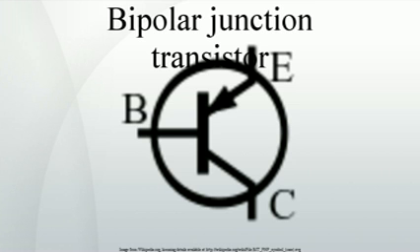Gummel-Poon charge control model. The Gummel-Poon model is a detailed charge-controlled model of BJT dynamics, which has been adopted and elaborated by others to explain transistor dynamics in greater detail than the terminal-based models typically do. This model also includes the dependence of transistor beta values upon the direct current levels in the transistor, which are assumed current-independent in the Ebers-Moll model. Small signal models.